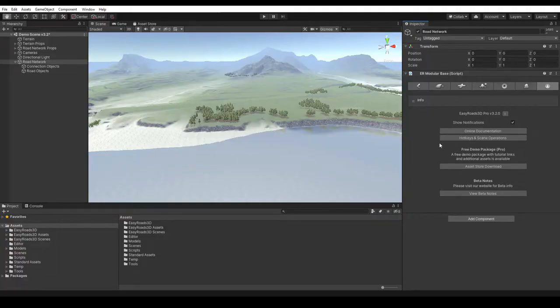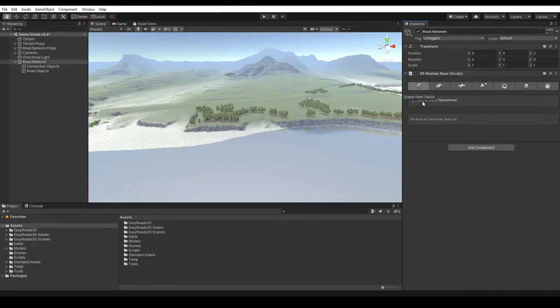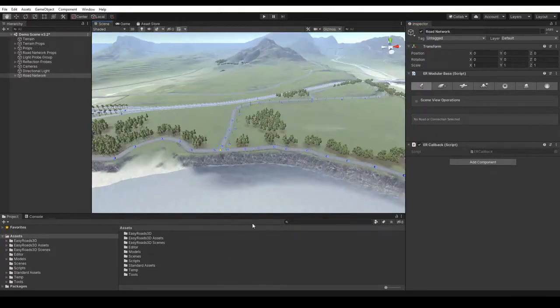So that briefly covers the EasyRoads3D toolbar. We have the Scene tab showing the selected objects, the New Road Object tab, the Crossing Connection tab, the Build Terrain tab where we can switch to build mode and update the terrain, the General Settings tab, the Side Object Manager, and the Info tab. Let's put all of this into practice and start with adding some roads through the New Road Object tab. We will actually do this in the demo scene, so let's move back to this scene and put the focus on an area where we can add some roads.